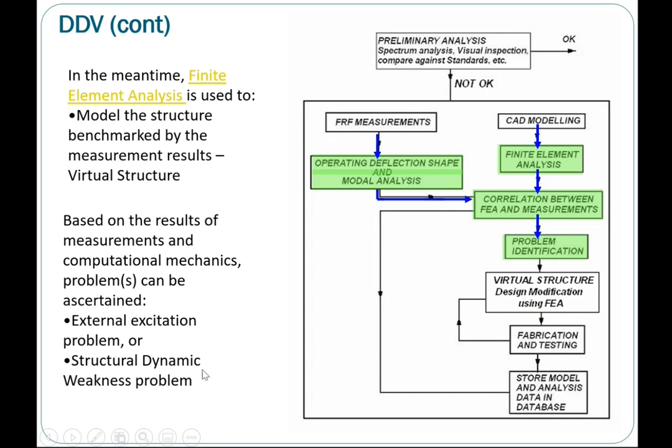So if you cannot see any natural frequency coinciding with the excitation frequency, and you still observe very high vibrations, particularly at your driver side, with a high 1x peak in your spectrum, then probably you can relate it to an external excitation problem caused by unbalance. So from here, you will know whether it's a force issue or a low resistance issue.